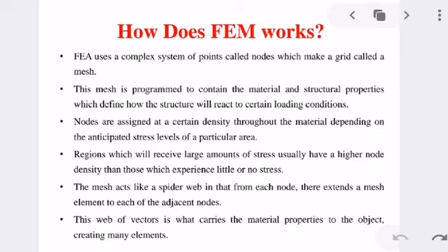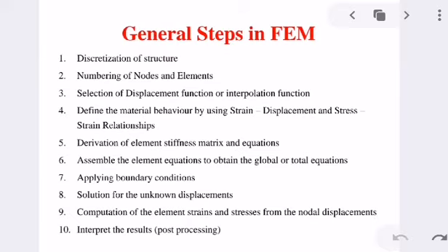Stress strain computations at any points in that element are then performed, following which the stiffness properties of the elements are derived. Elemental stiffnesses are then assembled to represent the stiffness of the entire solution region. This is how FEM works. It involves general steps.